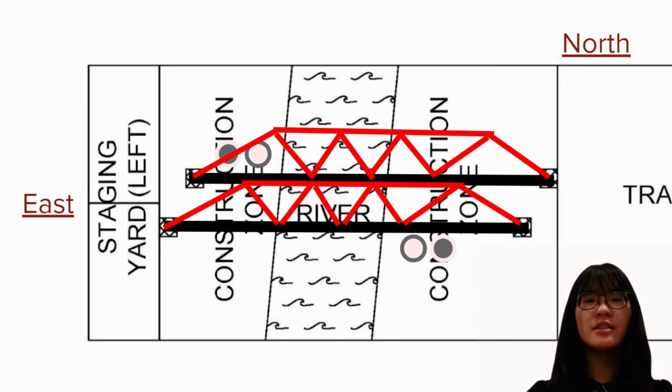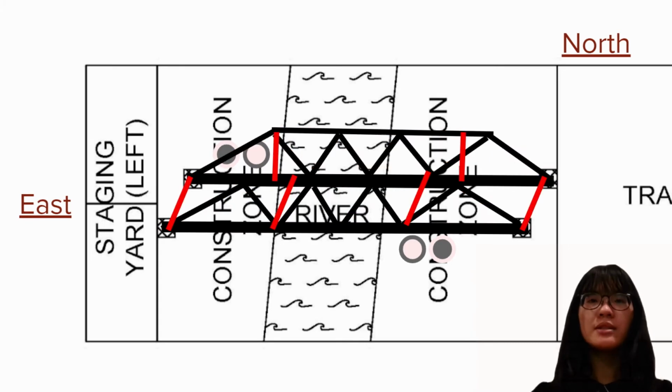The builders will then start constructing the upper course of the bridge with a similar building strategy as with building the stringers. Thanks to our construction-friendly connection design, all of our upper chord connections only require a bolt and a peg to connect and can also stay in place without bolting through first, which will further help speed up construction. Once the upper chords are constructed, we will finish up by connecting the remaining laterals.